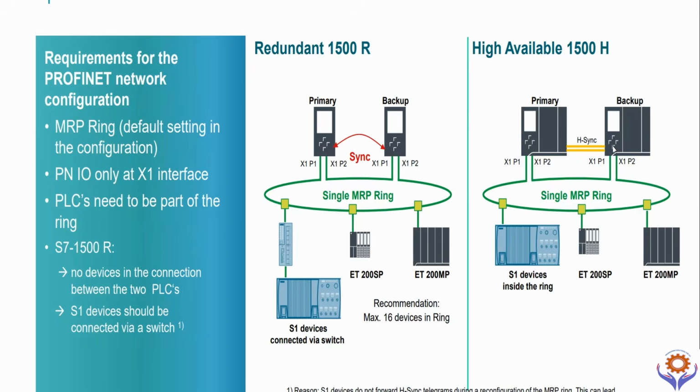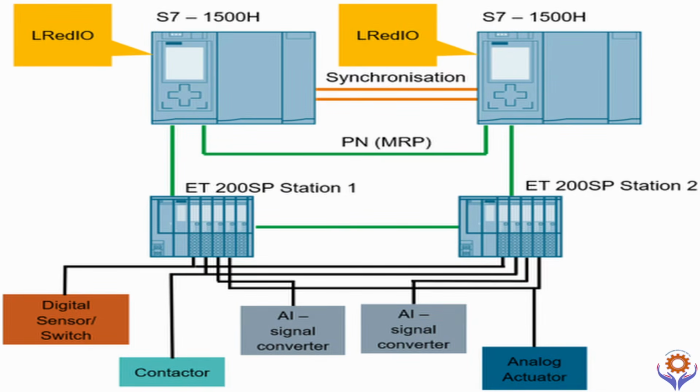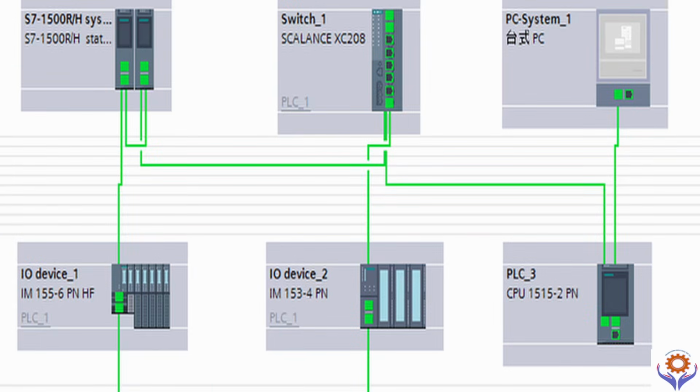Redundant system means a secondary unit is operating in parallel with the primary duty and both are sharing the demand. Standby means a separate unit that is not operating in parallel with the primary, but both are tightly synchronized between the primary and secondary PLCs.